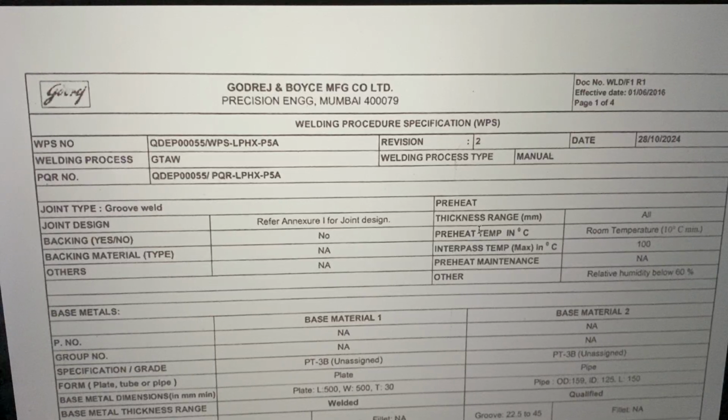Similarly, the preheat temperature. And the recommendation here is that if you are welding from the front side, the preheat should, as far as possible, be given from the other side of the welding, so that when you check the temperature, whether with temperature sticks or by infrared, the whole cross section, the whole thickness of the material gets preheated, and also it gives a uniformity.